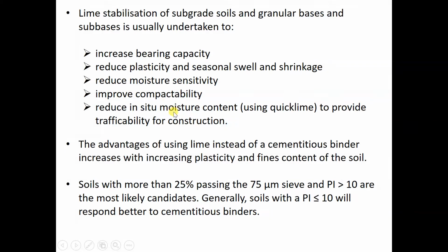Fifth, reduce the in situ moisture content. Usually liquid lime is used to provide trafficability for construction. You can just stabilize the soil with the lime without constructing the pavement, and then it can be used for the construction traffic.